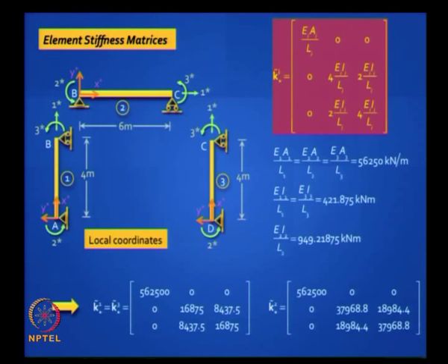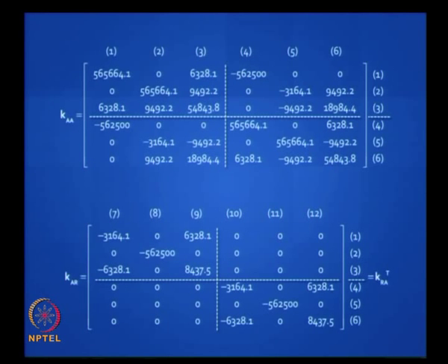You generate the structure stiffness matrix. You do it in 2 phases. First you do this KI TDI for the 3 elements. All this can be done by matrix multiplication. If you are doing manually also, it is not difficult, it is only a 3 by 3, 3 by 6. Then you add up all the contributions. You do not have to worry about slotting here because you got the TD, and you can generate,